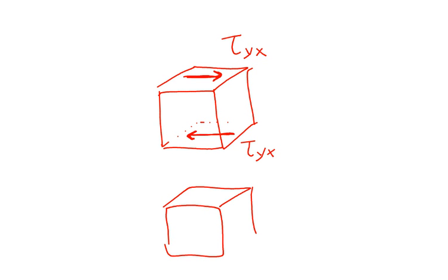is I need this, and the one on the left face going downward. These are tau xy, if you remember. Last time we defined these two as tau xy. Now, these two add up to 0, but they give me a moment. These form a couple with a rotation that goes counterclockwise about the z-axis, whereas the two up on top here, tau yx, give me a rotation that is clockwise about the z-axis.